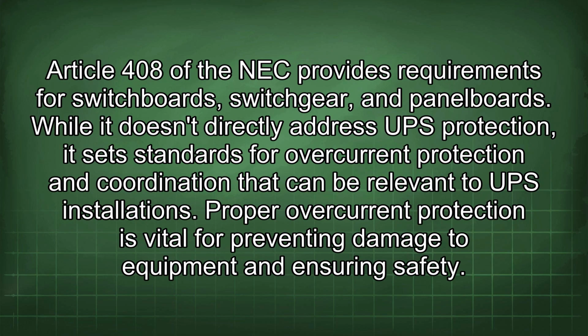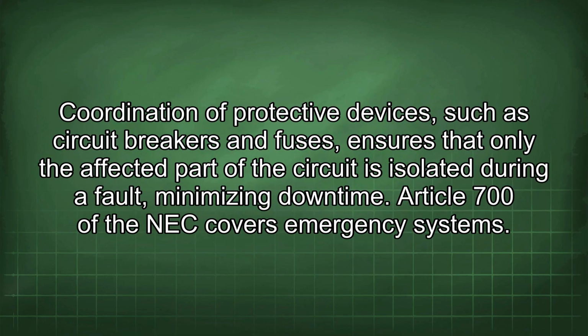Article 408 of the NEC provides requirements for switchboards, switchgear, and panelboards. While it doesn't directly address UPS protection, it sets standards for overcurrent protection and coordination that can be relevant to UPS installations. Proper overcurrent protection is vital for preventing damage to equipment and ensuring safety. Coordination of protective devices, such as circuit breakers and fuses, ensures that only the affected part of the circuit is isolated during a fault, minimizing downtime.